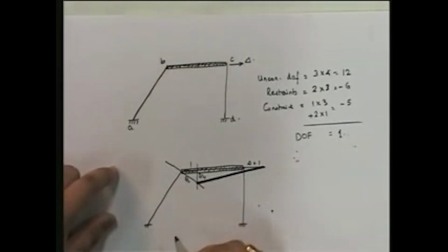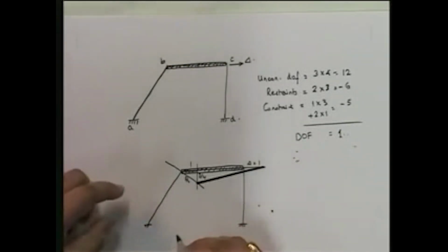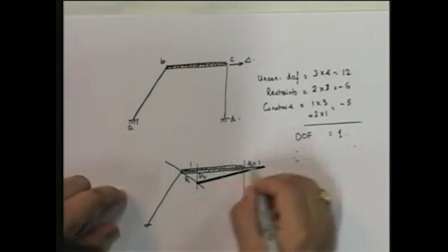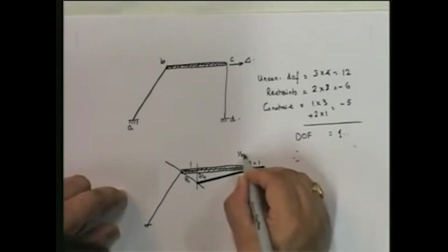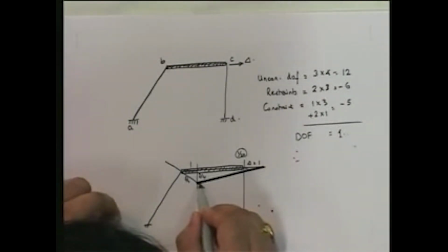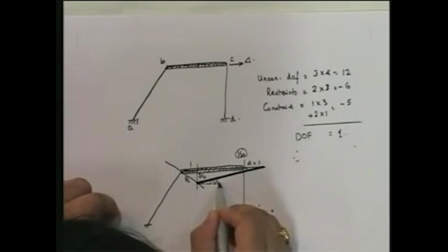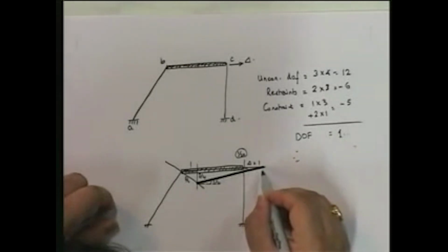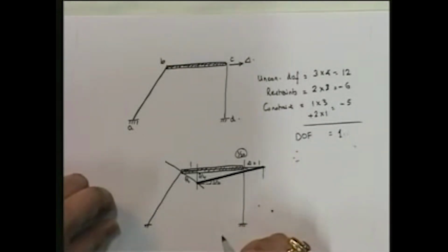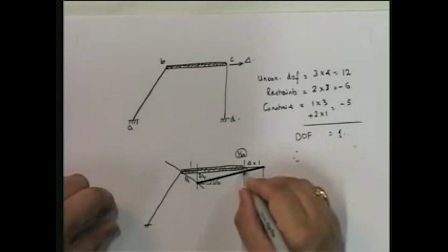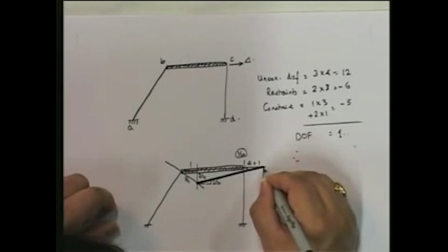It can only go straight. Now if it goes straight, what happens? Let's see. What is the angle here? 3 by 4 by 15, that's 1 by 20. Now note that means this also has rotated by 1 by 20. The interesting point here is that since this member has gone this way, there is no way that this tangent can remain in this way. Why? Because that will violate the continuity of the joint. Okay, so that means if this rotates by 1 by 20, this also has to rotate by 1 by 20.